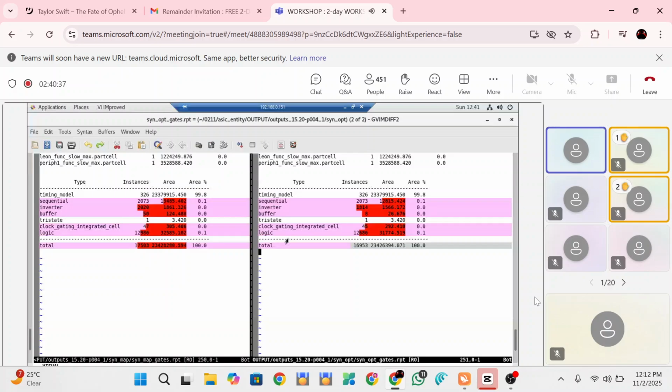I took a small design to analyze for faster processing for now, but in real it will have millions of gate count. It will take at least 5 days to run sometimes. You have to sit and watch whether it is doing its job or not. And in parallel to that, you have to run multiple runs to optimize that gate count to the number that is decided for your block. It is your 100% job. You can't say there is no way. There is a way, that we have to re-synthesize your actual logic. That's how the real fun will start with the physical design things.